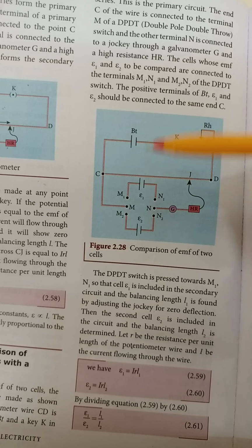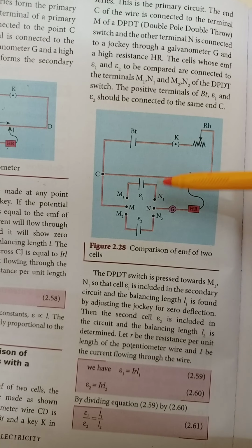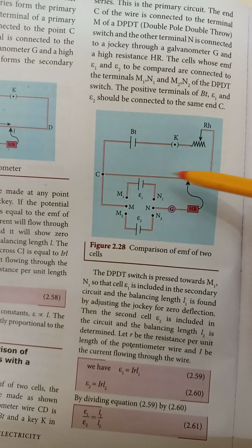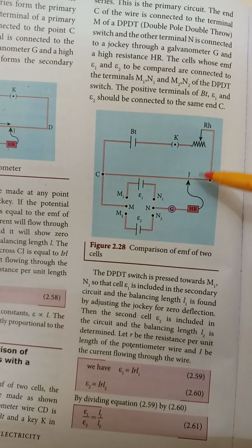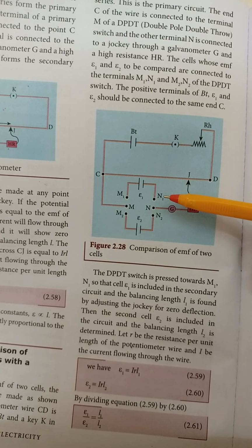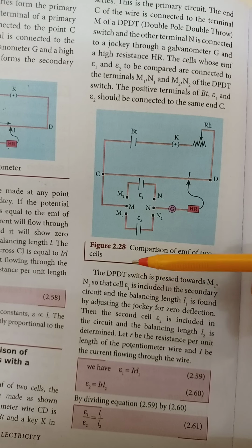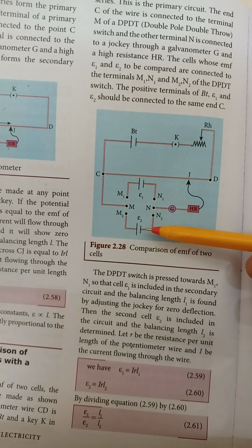Keep the DPDT switch on the side E1 so that cell E1 is included in the circuit. Now adjust the position of the jockey on the potentiometer wire so that at one position you will get zero deflection. Now measure the balancing length corresponding to the cell E1. L1 represents the balancing length for the cell E1. Next, keeping the rheostat in the same position, you put the DPDT switch on the side of the cell E2, so that the second cell E2 is included